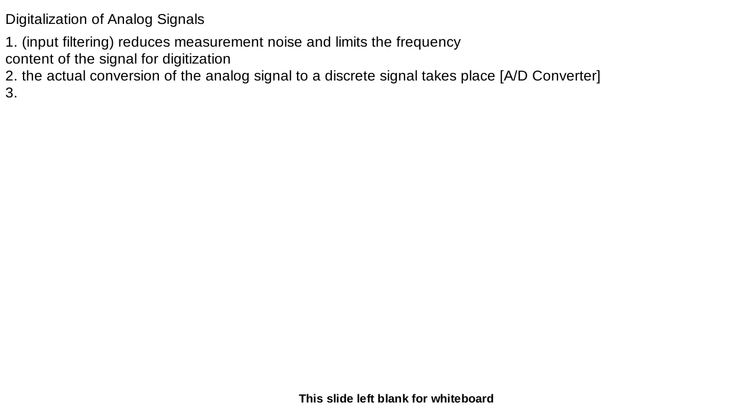Analog signals can be read into a PLC via analog input modules or input blocks. Such blocks come in many variants, but all have inbuilt filters, and the work of these filters is to limit the frequency content of the signal and also to reduce or do away with the measurement noise.